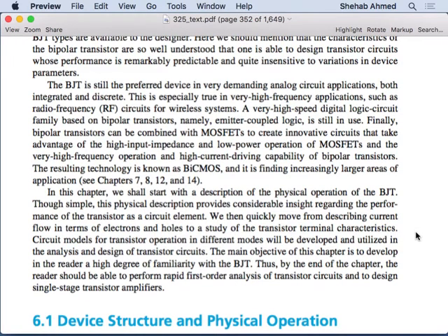So people have, especially in switching applications, combined the benefits of a MOSFET and the BJT in a technology called BiCMOS. It's a technology that includes both BJT type devices as well as MOSFET type devices together. And the power guys created what is called the IGBT. They created a BJT device, but with a MOSFET gate.